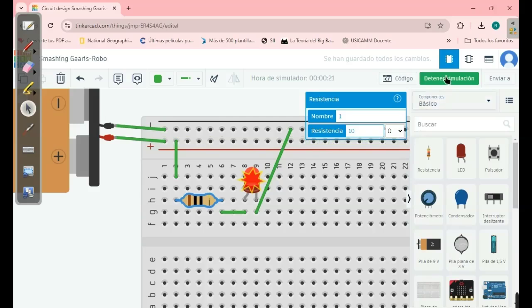In real life, the LED won't explode or emit smoke, it will simply stop working. It might look a little burned on top, or it might not show any signs at all, but it won't light up. For 9V, I recommend 1 kilo ohm.